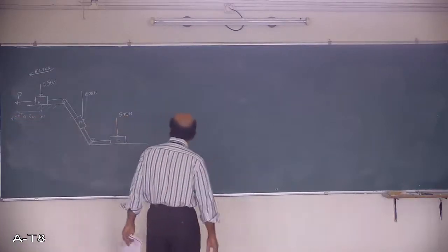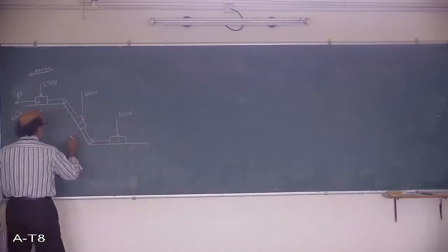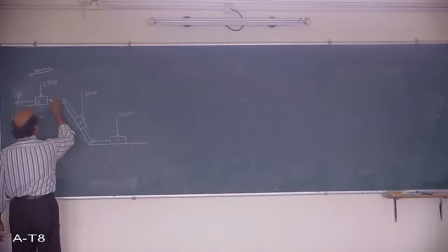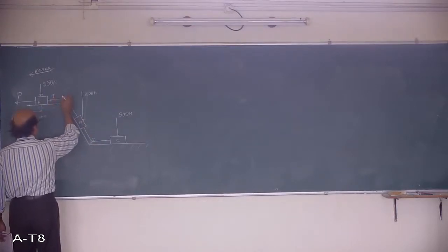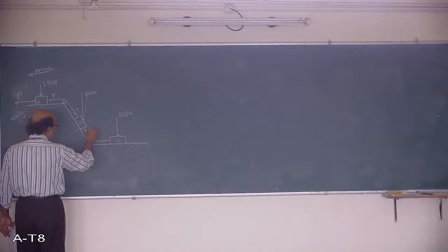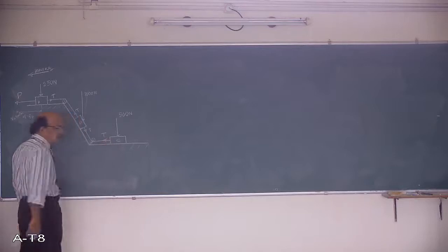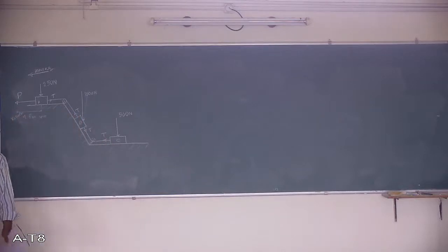My objective is to determine only the force P. But as you know, they are all connected by strings, and the string will always be under tension. They have not asked you to determine the tension in the string. In that case, you can apply the connected bodies principle so that T, being common for all, can be removed out. Directly you can apply one simple equation for all three, and you will be able to solve for the force P in one line.